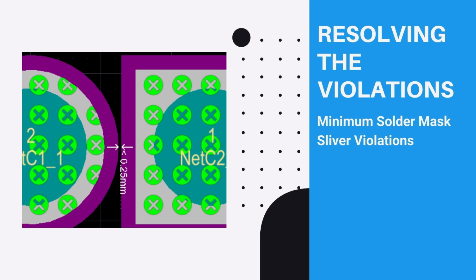Errors such as these solder mask issues cannot be resolved without consideration of the fabrication technique that will be used to make the finished board. For example, if this was a complex multi-layer board for a high-value product, then it is likely that a high-quality solder mask technology will be employed, which would allow a small or zero solder mask expansion.